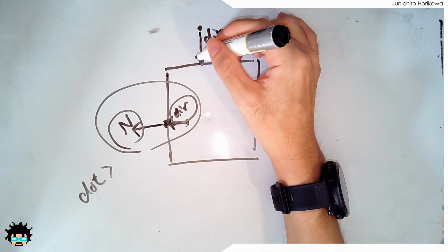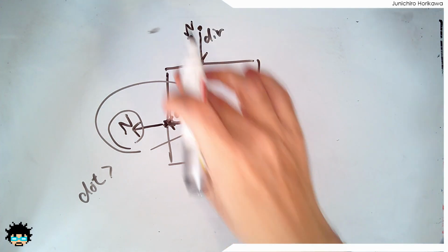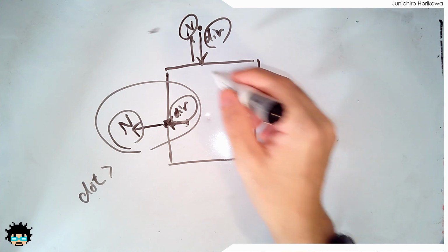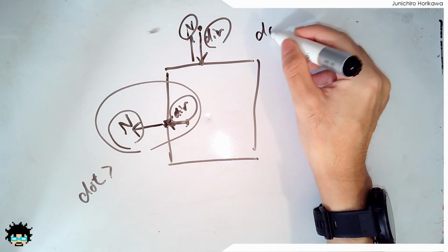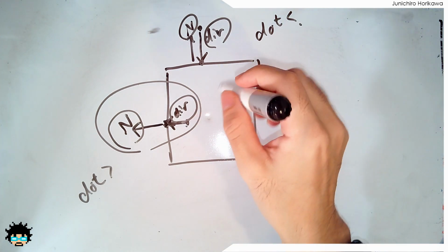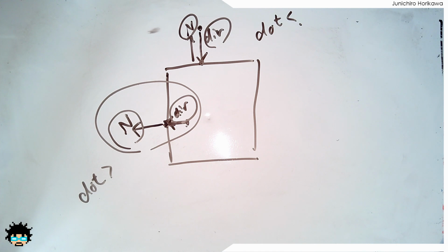And at this point, the normal direction of the primitive is this direction. And the dot product between n and direction, in this case, is negative, meaning the point is outside the box. So that's how you can determine whether the point is inside a primitive or a box or not, which works for any kind of geometry as well. It doesn't really have to be a box.